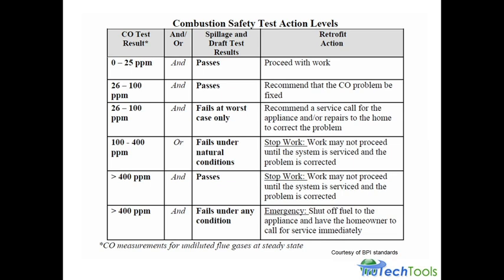You've got to realize the ANSI standard is 400 ppm. That's the maximum amount allowable in the stack, okay? We know as an industry we can get well below 100 ppm under normal conditions. There's absolutely no reason a furnace has to produce over 100 ppm of CO. Are there furnaces that do? Absolutely. Are there sometimes furnaces we can't repair? Absolutely. I've run across them.